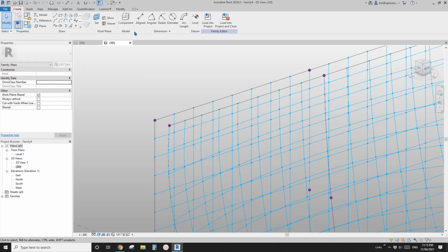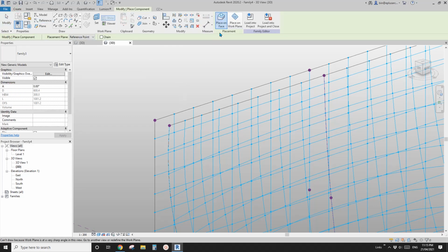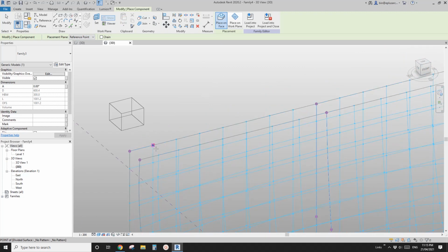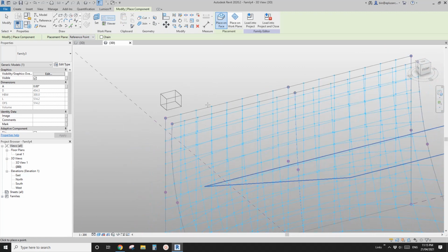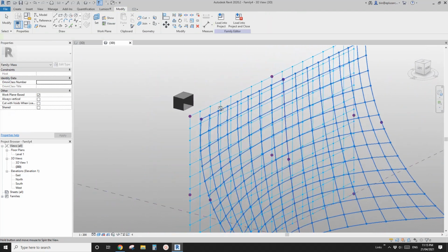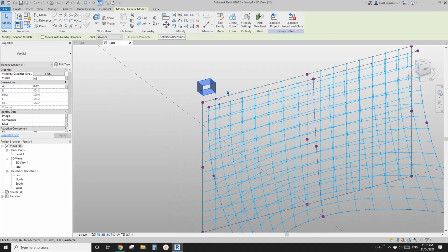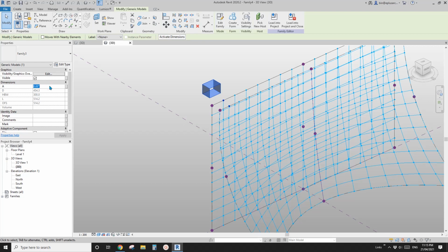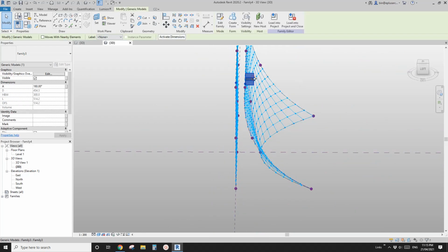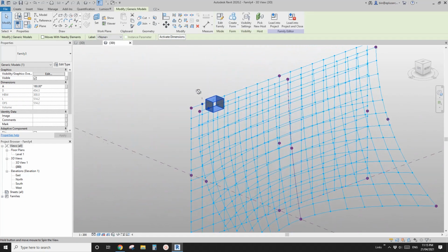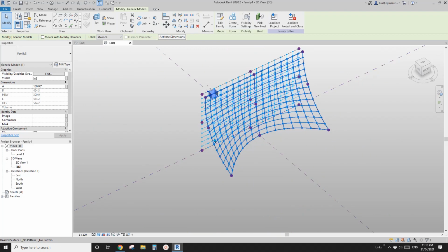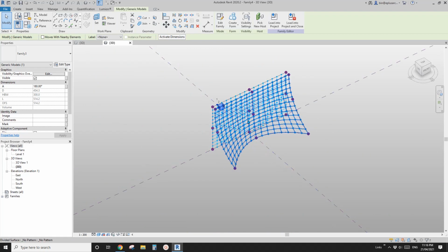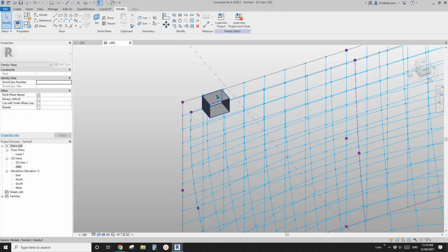We go create component, and let's try again, from here to here. What's going on here? Looks like we need to rotate it, so it goes this way. So I'll change this to 180. See? This is the reason why I added an angular parameter, because sometimes, for example, if you model it that way, you may need to rotate 90 degrees. So now this is one of them.